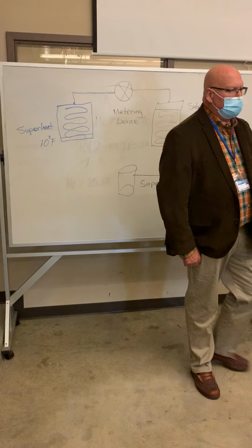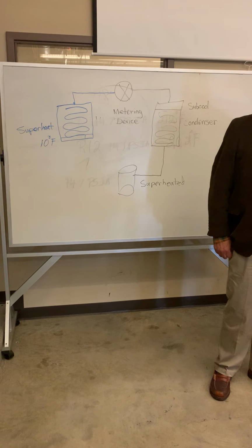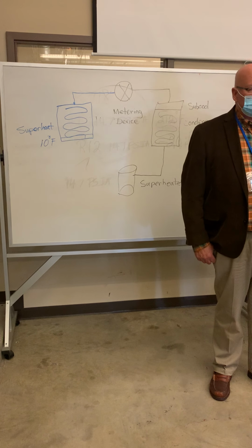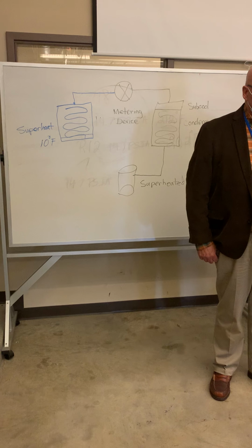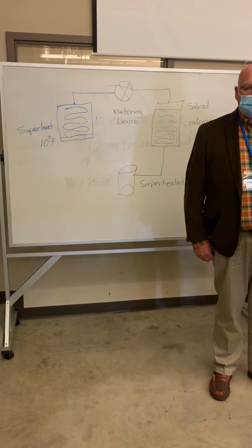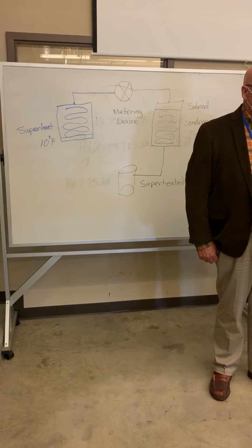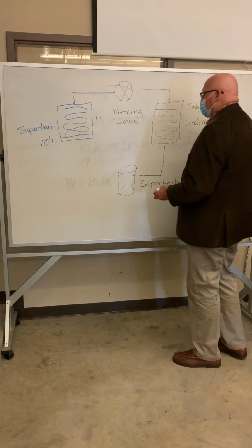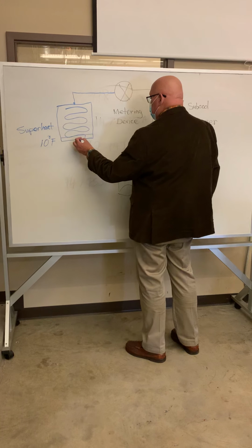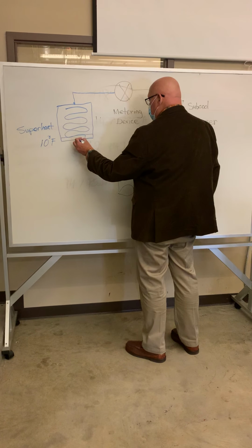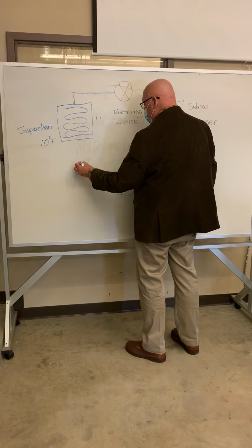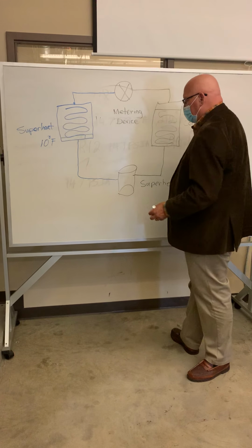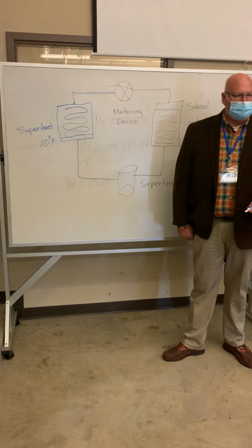It's now completely a gas, which means that it's safe for it to return to the compressor, because a compressor can only compress gas. An air conditioning refrigeration compressor only compresses gas. And then it leaves here, and this copper line that it leaves, and it makes its return run back to the compressor, is called the suction line.